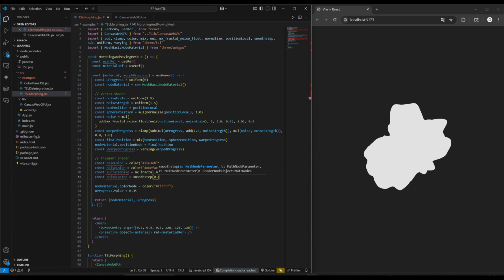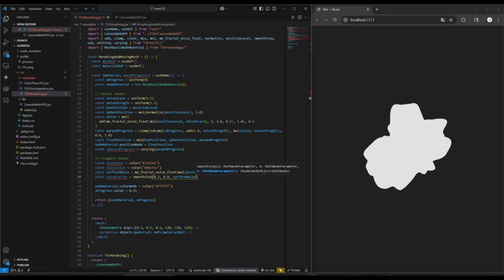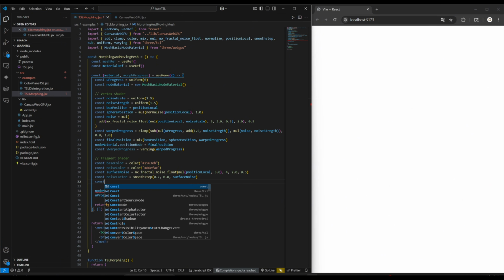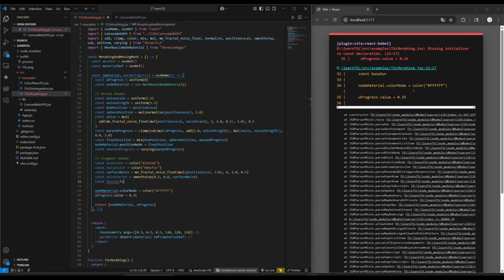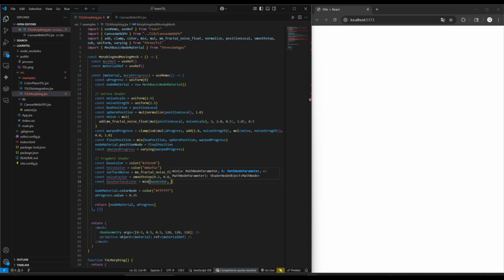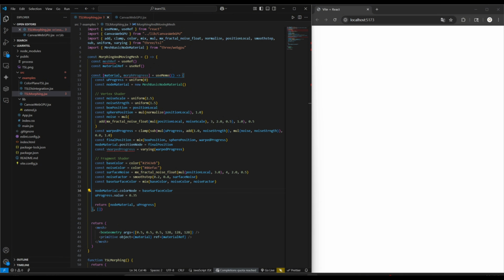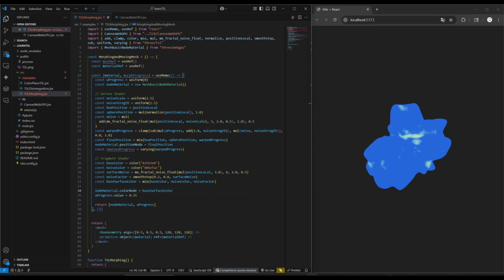Use smoothstep 0.2, 0.8 to widen contrast so the pattern is clearer without overexposing. Mix the base and noise first and plug them into the material. Now a blue-green modeled cube sphere hybrid appears.